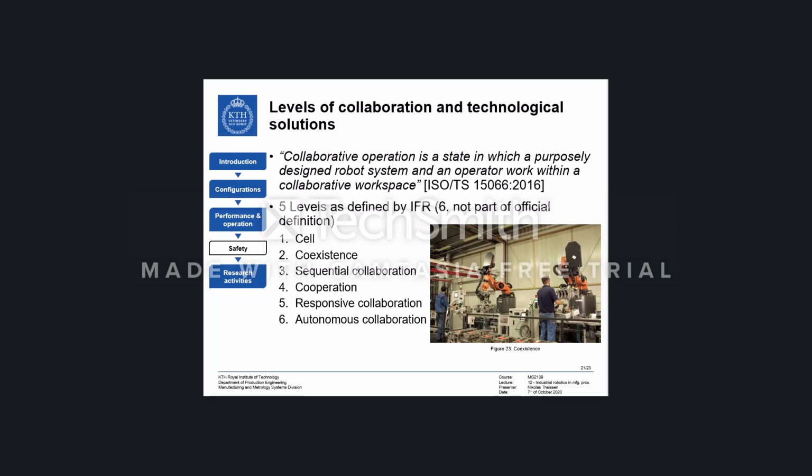Mechanical limits are used to reduce the working area for the robot. Historically, the fences around the robot system have been outside the robot's maximum workspace. Due to the complex cell layout design, it wasn't possible to mechanically reduce the working area of the manipulator in most cases. In particular, the bending backwards kinematics are extremely difficult to limit to the working range of axes 2 and 3 because the robot's working range is needed for the front area, but it should be limited in the area behind it.